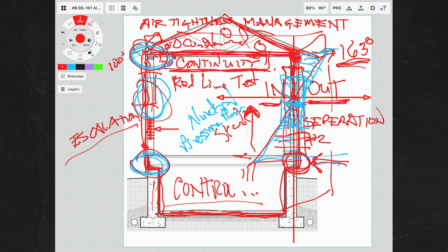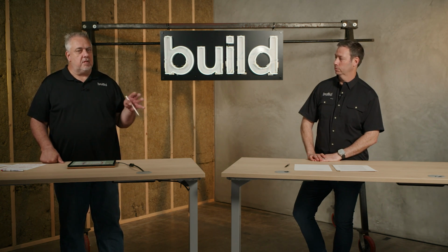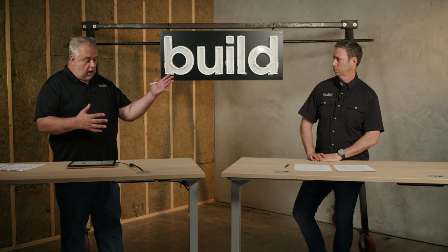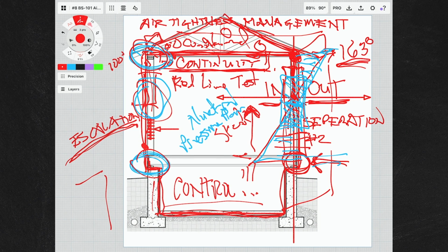But the basic premise of escalation is the minute I introduce an airstream to a building, well, things can jump on that airstream. And this is why air tightness and water management are linked as control layers, right? Joe had that really cool image that I know you've seen. It's a piece of drywall, right? And he has a 1-inch square hole in it.